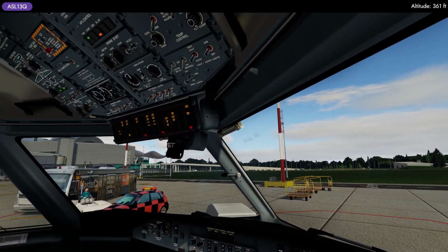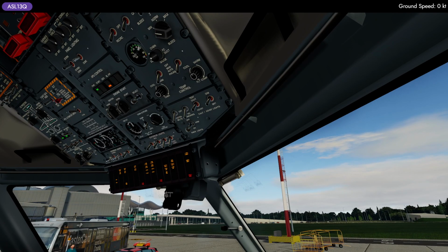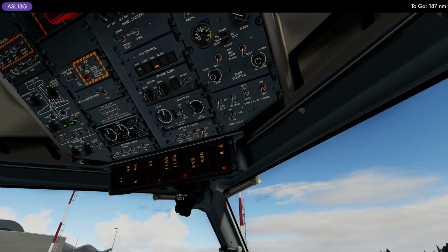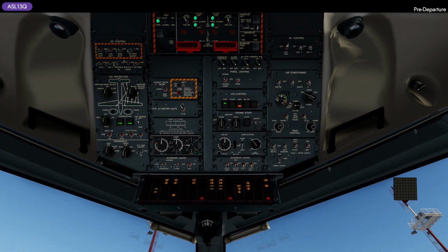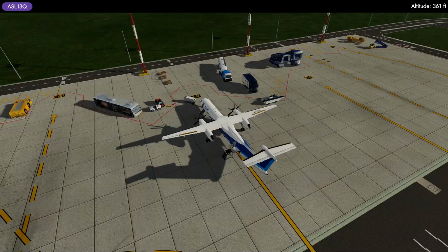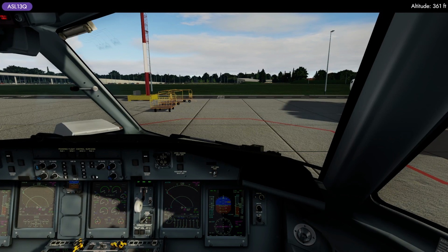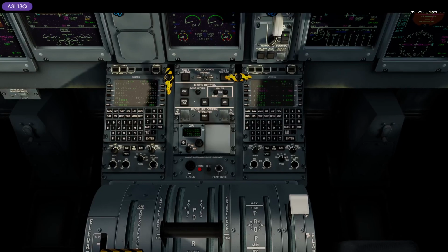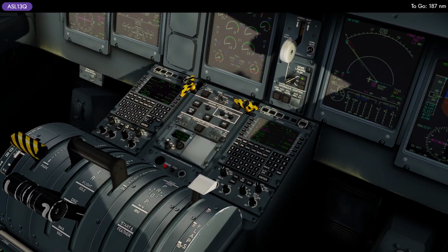Our APU should be on, yes. So let's switch to the generator and let's turn on the bleed there and open the bleeds, but keeping it to a minimum. And now since we have the generator on, we can turn off the external. As you can see, the generator turns green, and we do the main bus tie off. So from this moment we are actually on the APU. Boarding has been completed, and the auto feather test has passed, so we can turn it off.